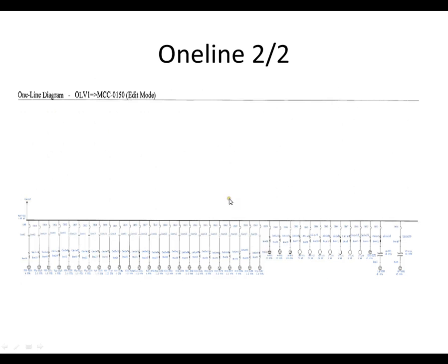And then from there, this is the motor control center, or MCC one-line. In this area here you see the compressor hot starts, which basically heat up the oil and the coolant in the compressor so that when it actually starts it'll be closer to operating temperature. It makes for easier starting, easier compression and use rather than starting cold.